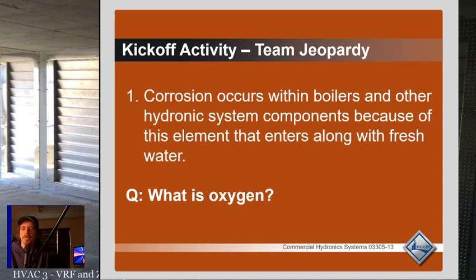Alright, steel, copper works well on boiler systems because, again, the copper is not going to get thin as quickly as it would with freshwater systems because there's less oxygen and minerals in there to cause corrosion. But this assumes that when you start that boiler system or chiller system, you purge all the air out and it's never opened, okay?